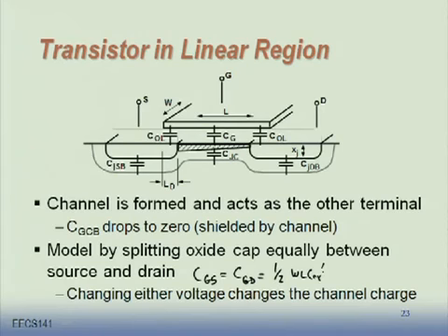How would you test if that is a valid split? In SPICE. Or maybe analytically. How would you test if this is a valid split, 50-50? Or let's start with something simpler. AC current is good. Charge. How about charge? Inject some charge and figure out how does it distribute. And you'll find out it distributes evenly. Right, you had this capacitor, and what did we do? We split it into two halves. One half is here, the other half is here. When we sum them, two capacitors in parallel are equal to CG.